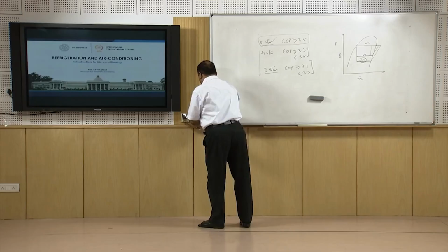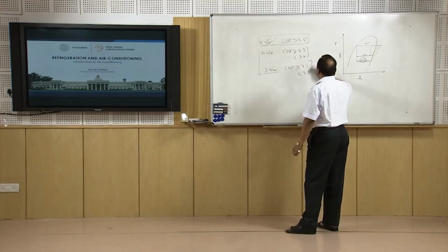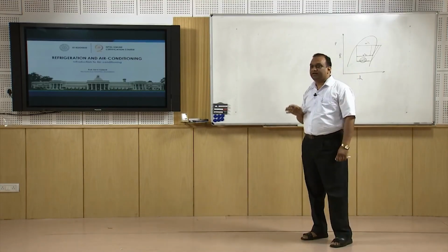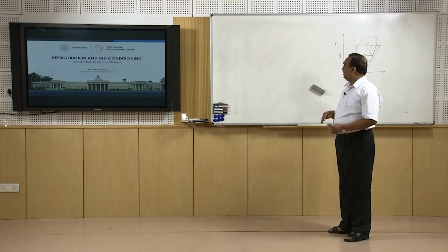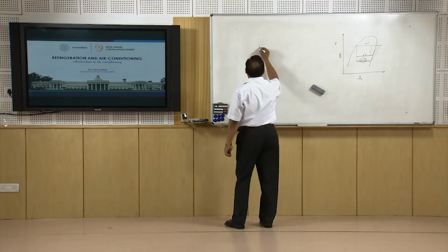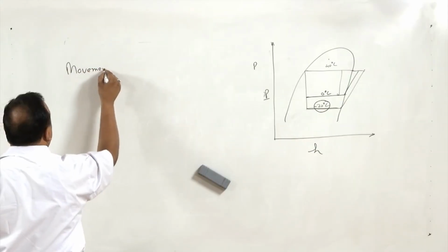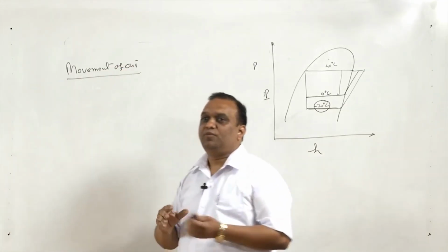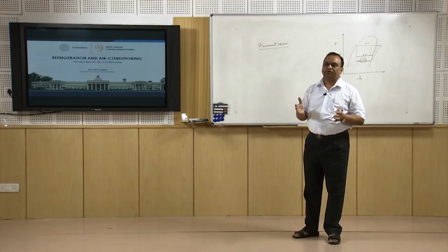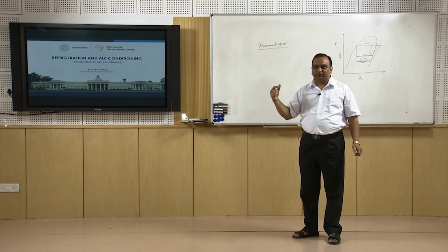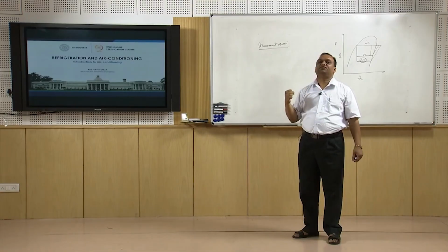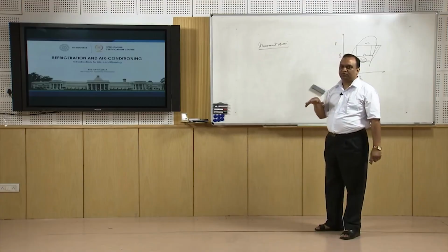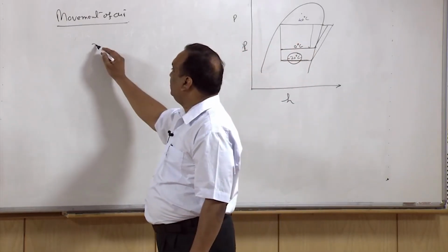Now, after this star rating, this is about the heat transfer, but air conditioning involves not only heat transfer or maintaining the temperature, it also involves the movement of air. The movement of air in a residential building should be such that in any part of the room the temperature difference should not be more than 1 degree centigrade, or if it is a 3 room or 4 room set, the temperature difference should not be more than 2 degree centigrade.